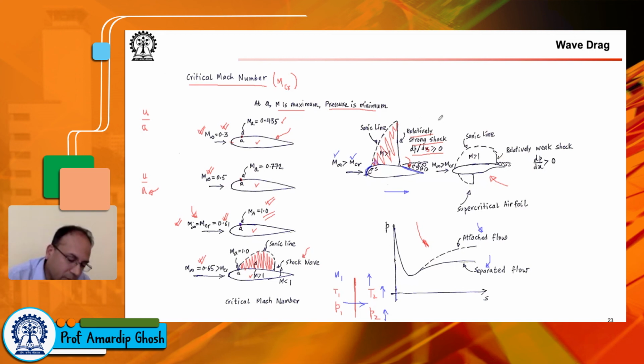So when you operate between 0.3 and 1, you have to modify your Cp to adjust for something known as compressibility corrections. So you have to correct for compressibility effects, and you will see that the effect of compressibility, say for subsonic flow fields, but flow fields which are compressible, because remember, I don't know whether we have covered this in one of our initial slides, or maybe I'm waiting, because I want to cover Reynolds transport theorem before we get into the discussion of what is compressible flow, what is incompressible flow.